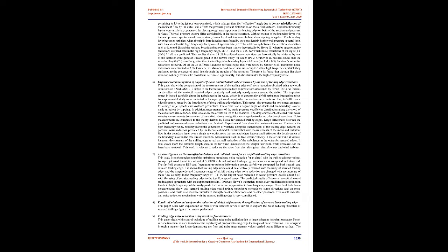5. Airfoil self-noise reduction by non-flat plate type TE serration. This paper aims to reduce the airfoil trailing edge self-noise by employing non-flat plate type trailing edge serrations. This configuration offers better structural strength and integrity, as well as a more straightforward manufacturing process compared to the conventional flat plate type serrations. To increase the effectiveness of the proposed serration geometry, a hybrid configuration composed of a non-flat